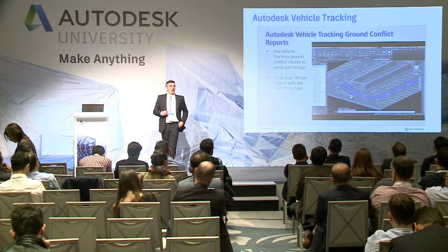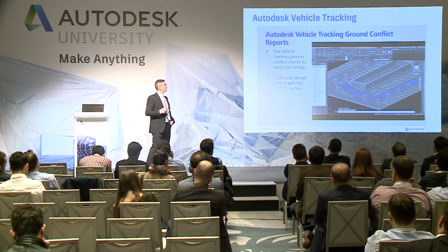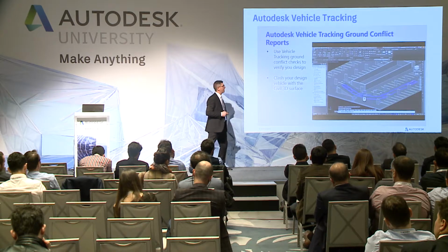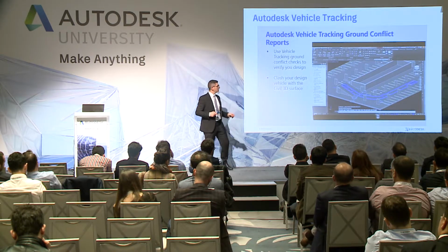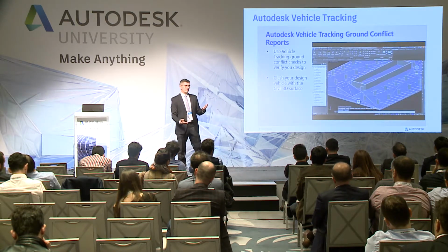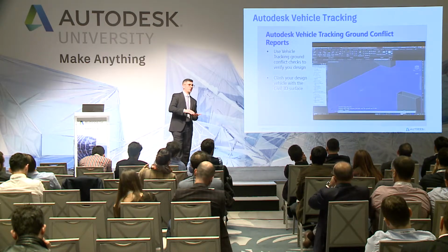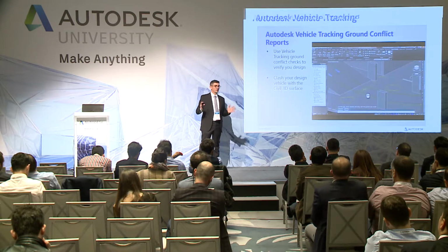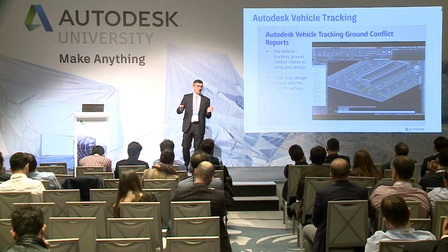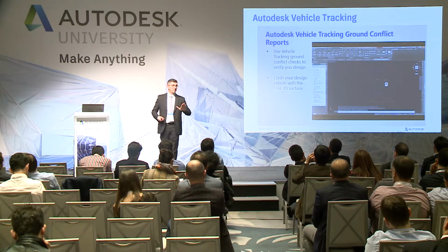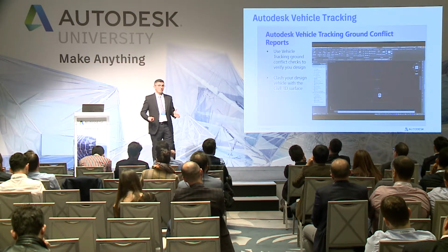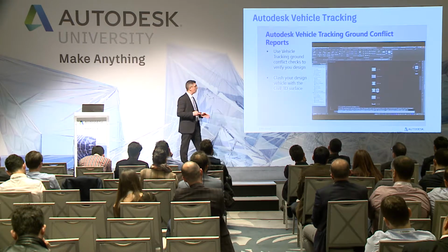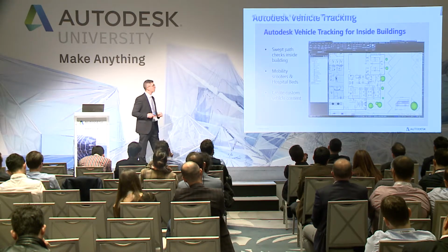One important thing about this type of element is that we can also manage conflicts. If the space between the body of your car and the body of the floor is not enough, you have this type of representation that means, look, you don't have enough space, please check. It may mean that you need to change the slope of your ramp, or understand what happens if your vehicle moves on top of this representation.